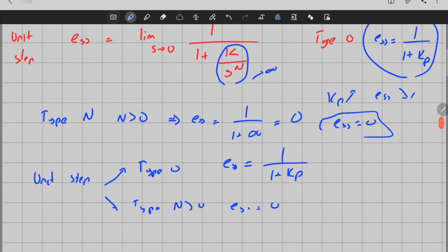That's great. Okay. So if you want a perfect steady state error under unit step input, it says that you should change the type of the system, which you can do by changing your controller type. If you're okay with constant steady state error, but you try to minimize it, what you can do is you can change the static error constant of your system.